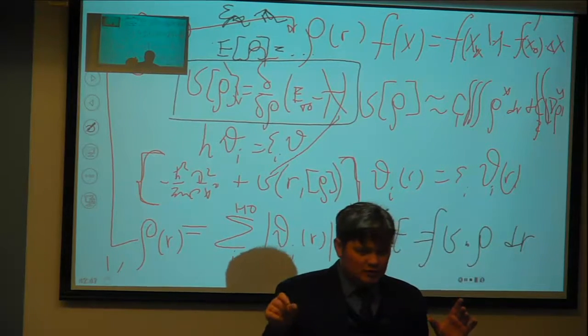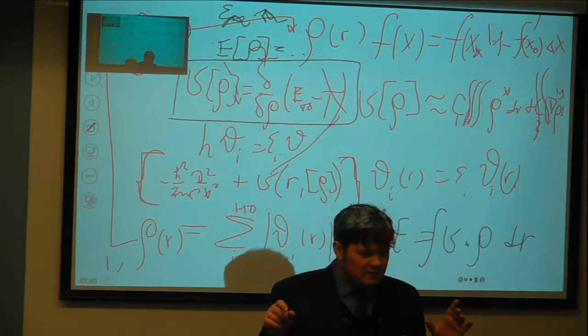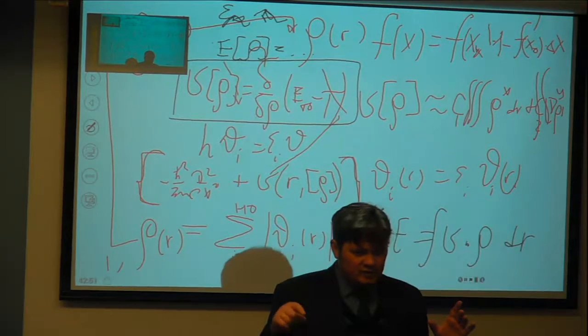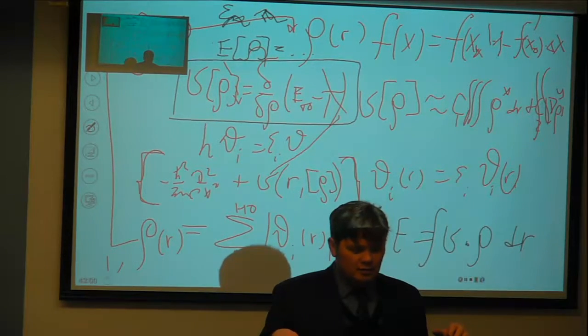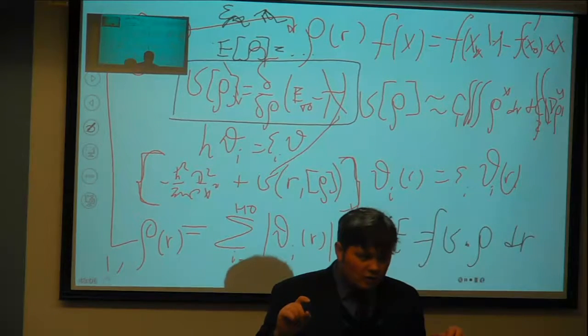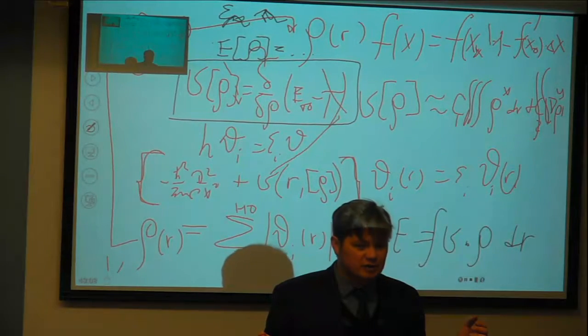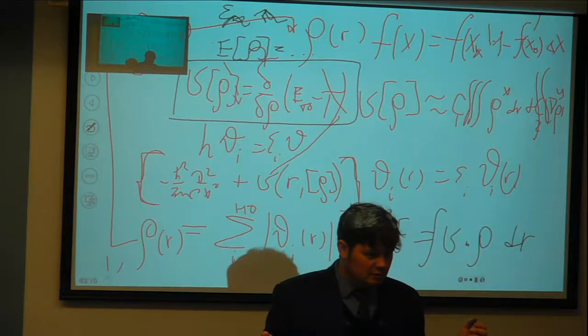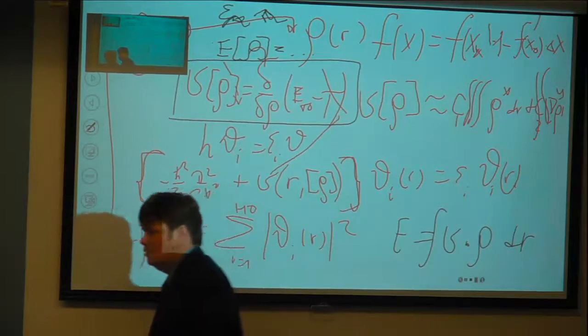And one of the columns includes the difference between previous and next energies. And as soon as this difference goes less than whatever you request, it stops. And either goes to computation of observables if you have 0 ionic iterations, or it goes to ionic iterations itself. Make sense? So you do watch it.